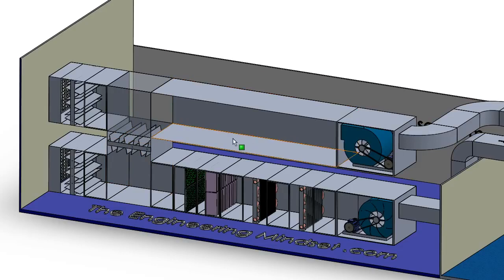And it will usually depend on outside air conditions for one, and also the level of CO2 in the room or in the return duct here. And if the conditions are right, then it will channel some of that back in, and that means that the heating coil will not need to do as much work, or maybe the cooling coil, maybe the humidifier will not need to work. So you will save money by returning some of that air back into the system.